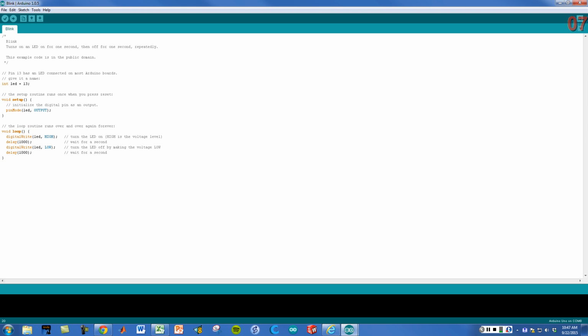Now we want to wait for 1 second. Because otherwise, if we didn't have this next line of code in, we would just go right to the next thing and turn our LED off and you'd never see it. So we need to leave it on for a little bit, because the Arduino is running each line of code very, very quickly. So now we're saying, all right, Arduino, just wait a second.